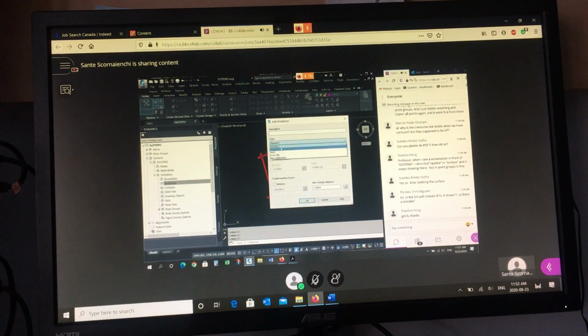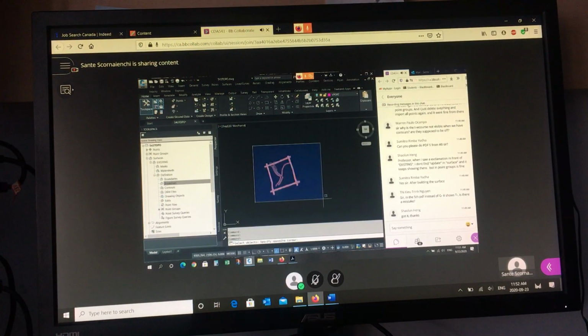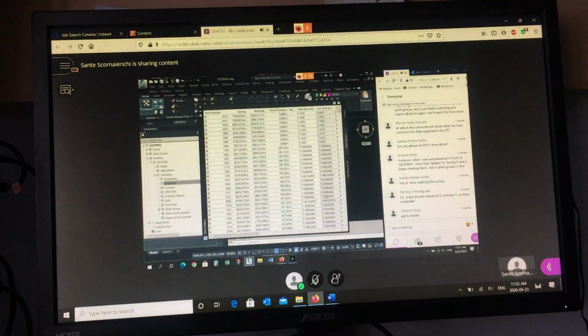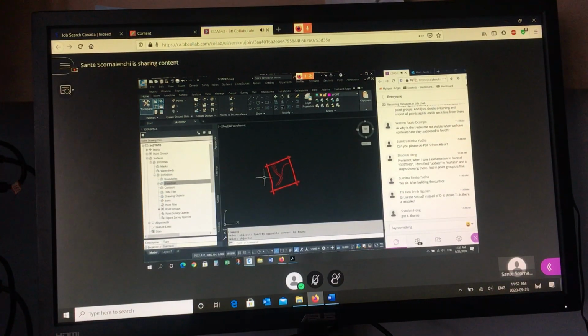To define those break lines, you click on break lines, right click, add, change this to proximity. I don't want any additional points with zero elevation. I just want the relationships that these represent. Say okay. Select everything, hit enter, and you're done. Now, if you didn't draw your water course lines, you'll have to do this again with the new polylines that you draw. If you draw them first, you can create your break line definition all at once.